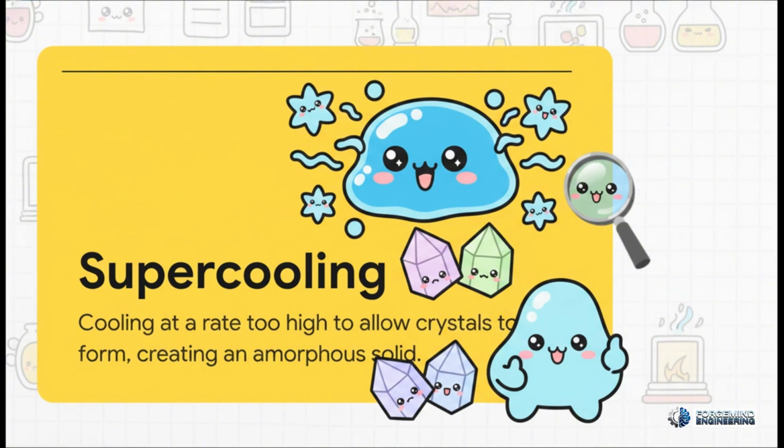So, to engineer glass effectively, we have to remember its foundation, that it is technically an inorganic product of fusion, right? And supercooling is the precise mechanism that makes the whole thing work. By chilling the melt at a rate too high to allow any crystals to form, it bypasses crystallization entirely and forms a rigid, amorphous solid. It behaves mechanically like a solid, but structurally, it's like a liquid.